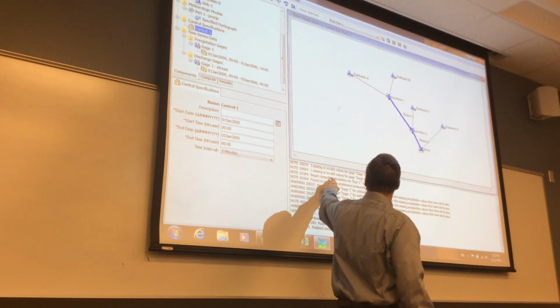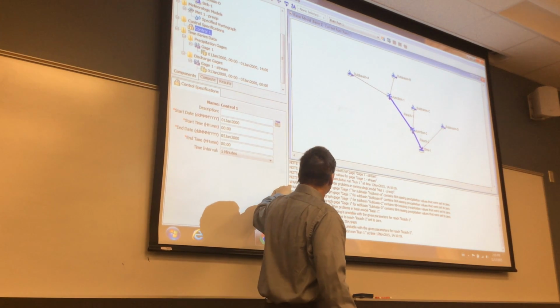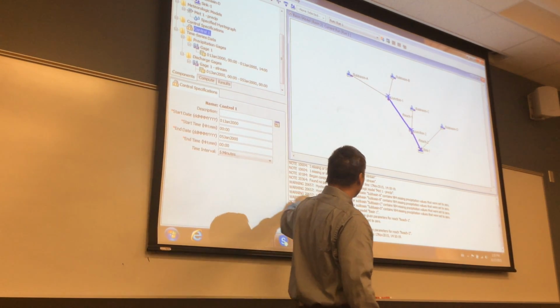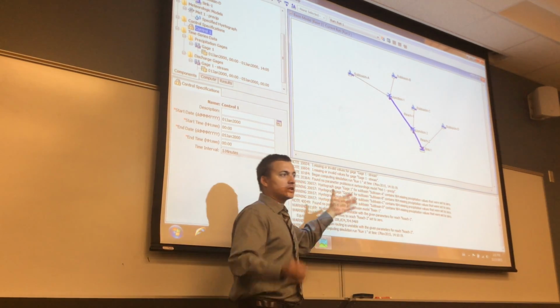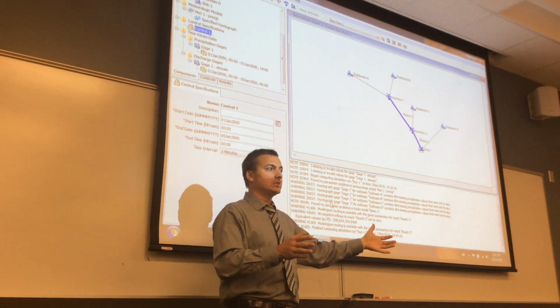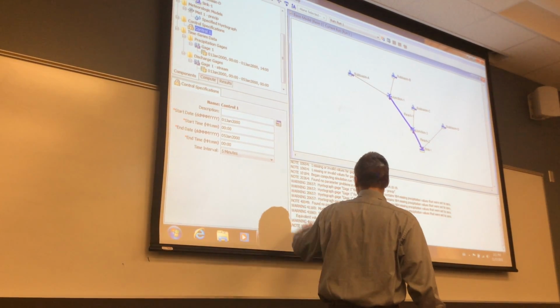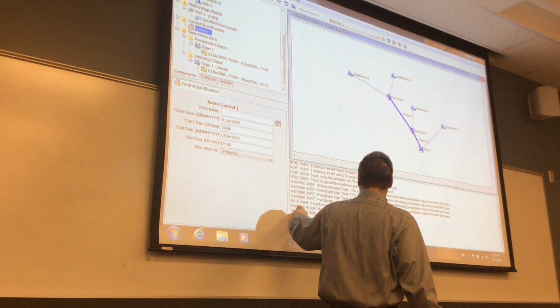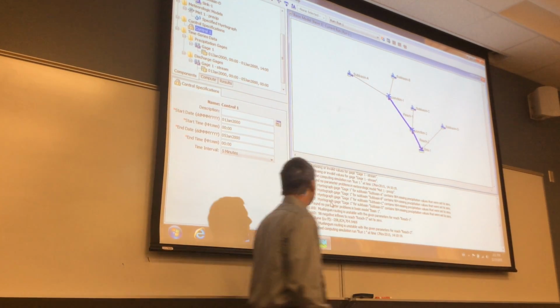We have one missing or invalid value for gauge 1. That's fine. And then we have a lot of missing precipitation. We knew that because we only had 14 hours of precipitation, right? And we're trying to run it for much longer. Okay. And it's telling us that the Muskingum routing is unstable, so we'll see that. Let's check that.